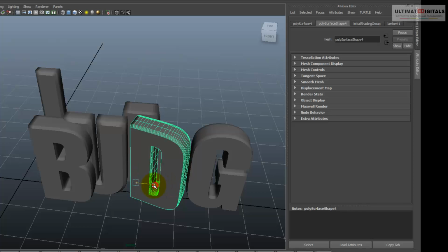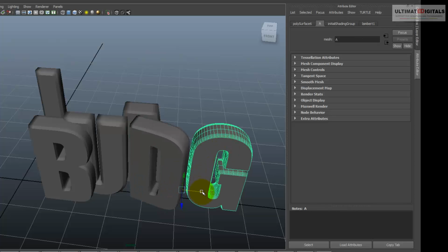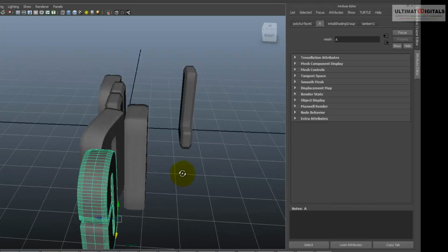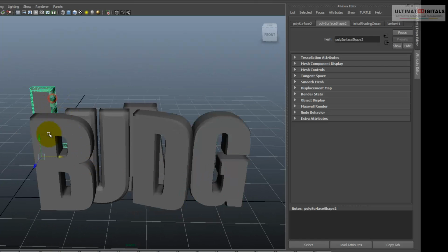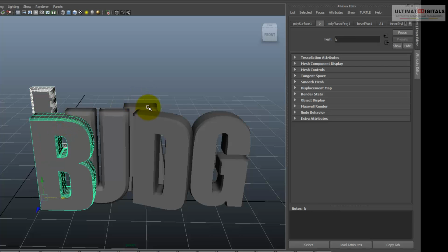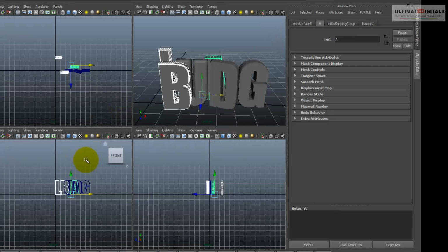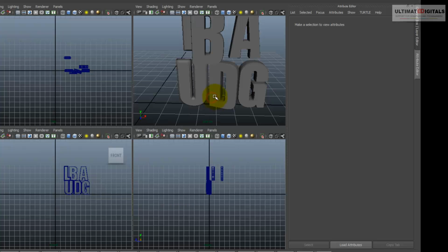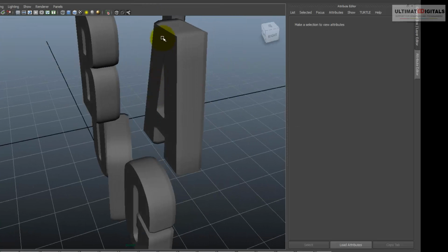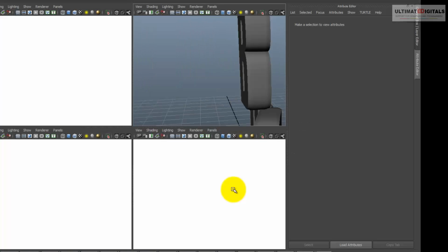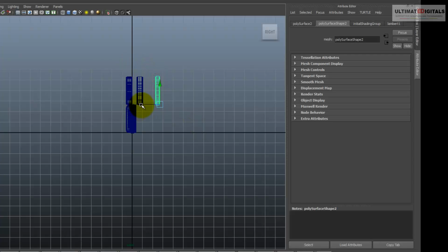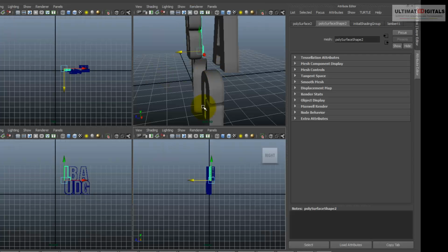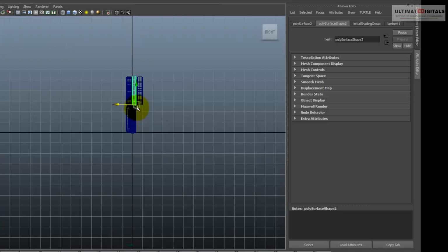Make them as close as possible to make the shadow effect be seen. After that, click the letters L and B. By holding Shift, you can select multiple objects. Right now select these and I move them up and then here. Of course their positions are not correct, so correct their positions from here. That's the letter L. I am changing between the views by pressing space, just for information.